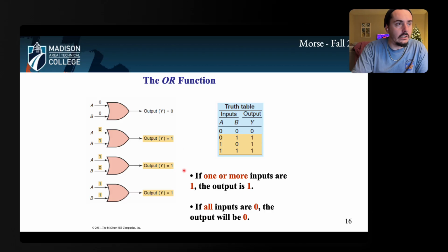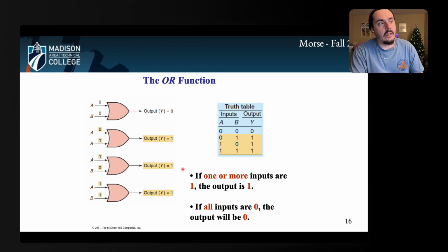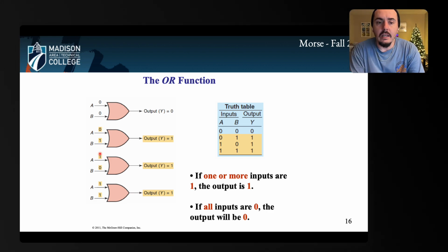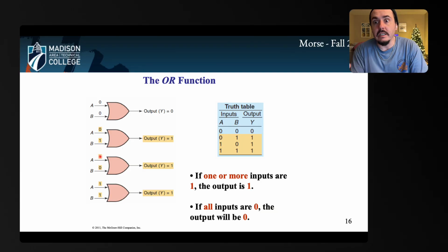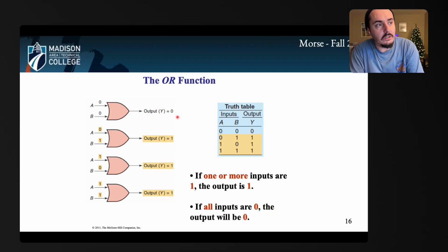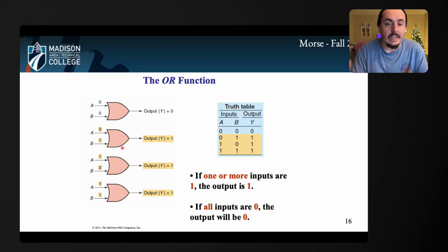And so this is, again, the outputs of the function neatly put. So, like I said, if either one of the inputs is yes or true, then the output of the OR function is true. So the only time the output is zero or false is if both the inputs are zero. Otherwise, A or B works. Doesn't matter which one. I can have both.